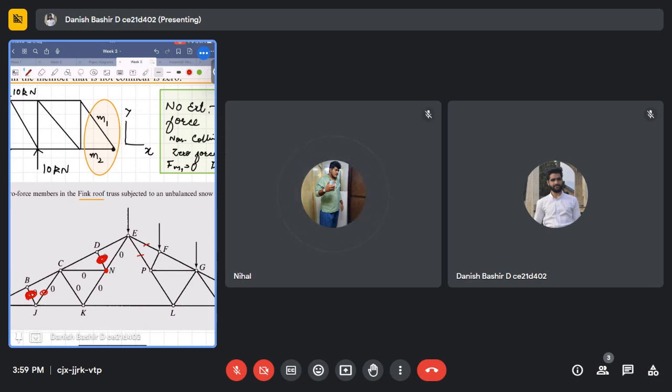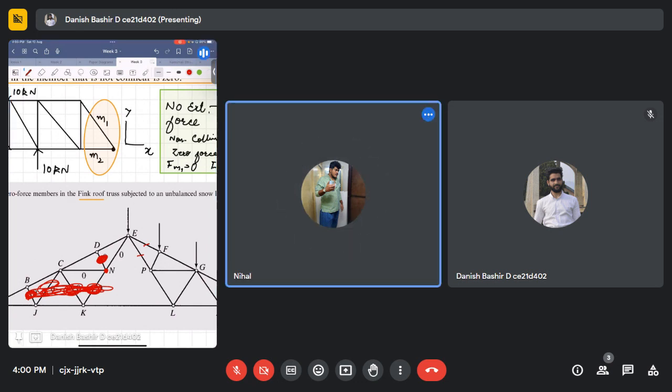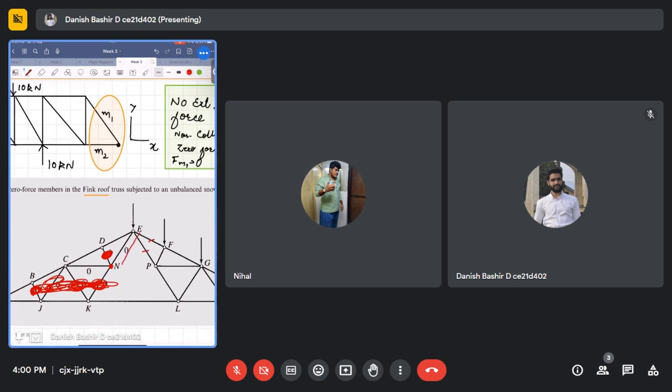Okay, so then this is collinear, this is collinear. This will be zero force member. This will be zero force member. Okay, deleting all those which are zero force. These all are deleted here. Are you getting my point? Yes, sir. Now comes the NE member. Now look at this NE member.